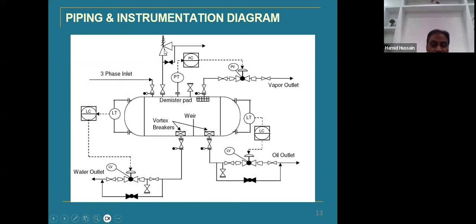I am telling you because I have experience, but how will you know that? I'll show that standard. For example, here this is the flange, and these are the flanges for the level transmitter, and then these are the two lines and a differential pressure transmitter actually, and that is nothing but a level transmitter. This is a dotted line. I'll show you the significance of this, and then this is the significance of the hard output going to the level control valve.